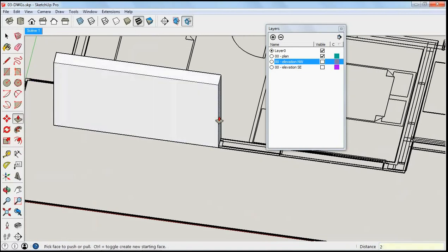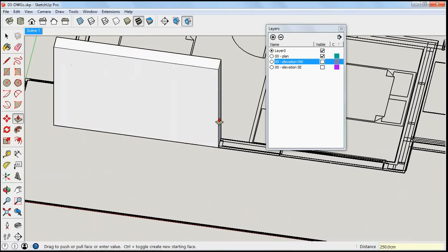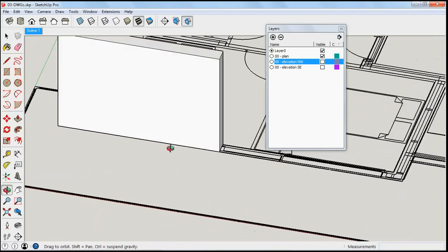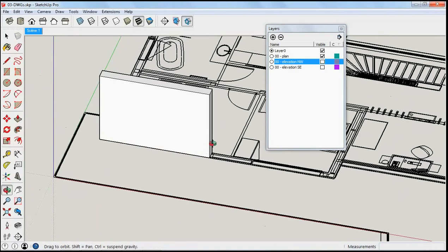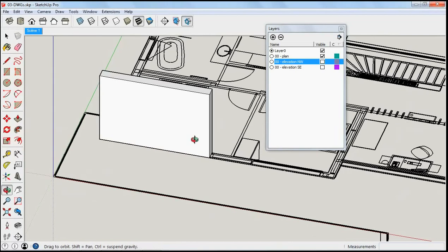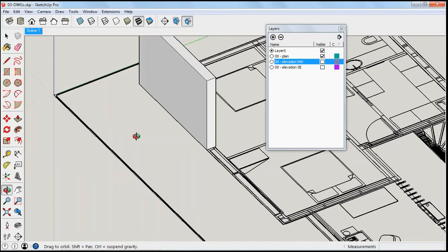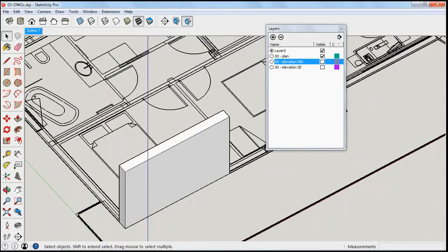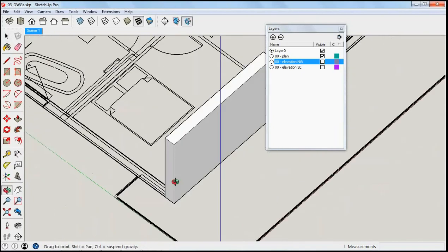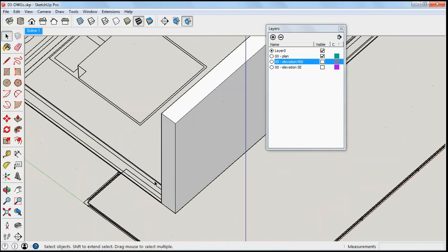And over here I have my wall height as 250 centimeter. So as you see, it is not necessary to set any of the units or parameters. You can directly key in your values into this box, the dimension box over here. So this was the traditional method of constructing the model. Now I will just showcase a few more methods with which we can approach this.